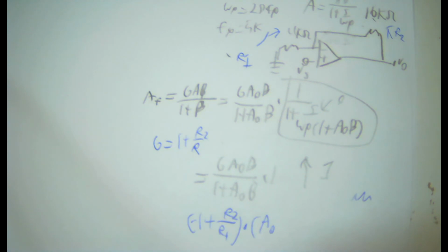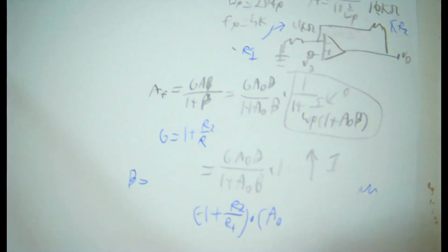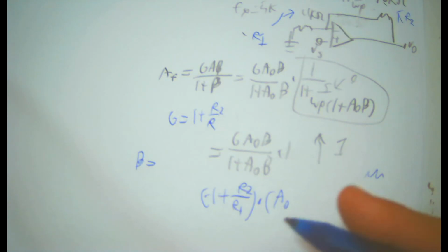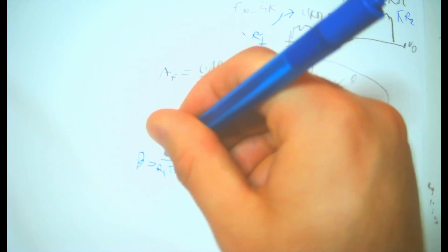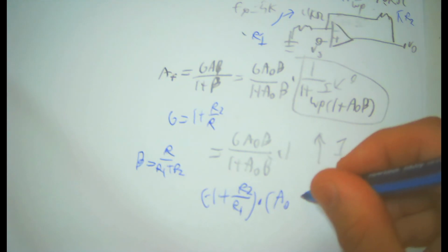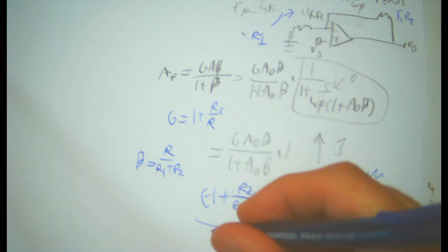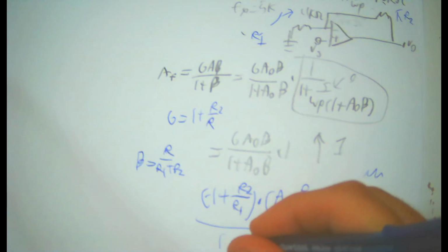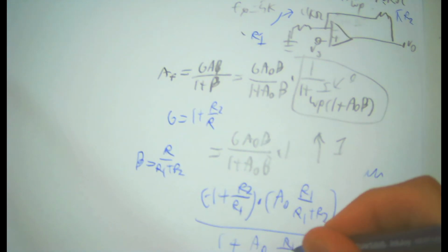How did I get that? Let me think. 1 over 5. I should have figured this out really fast. 4 over 20. Okay, beta. According to my notes, beta is just normally like this. I'm sorry if again I'm a little iffy on this because I'm way past this topic, but that's okay. The beta is just naturally this, from my notes at least. So this is straight up going to be R1 over R1 plus R2, and then all over 1 plus, hey, it's just gonna be beta because this right here is beta, so it's just gonna be beta again.